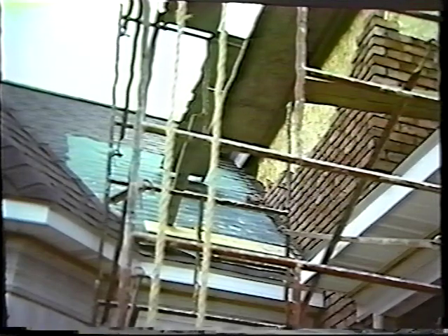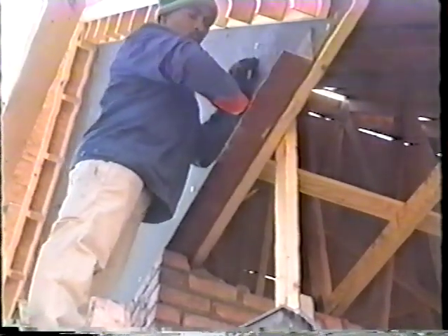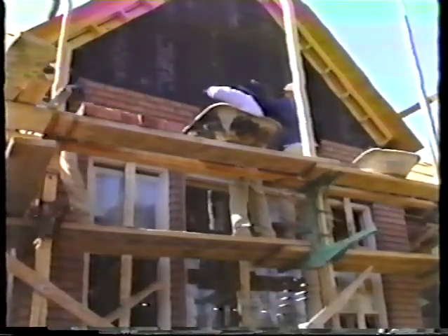The preferred means of supporting brick on wood is to have a steel angle bolted directly to the wood framing members to support the brick. The wood framing members are designed to resist the load. As an alternate, a steel angle may be attached directly to a roof rafter. The rafter must be strong enough to support the load. The brick must bear on the rafter and not on the roof sheathing alone.